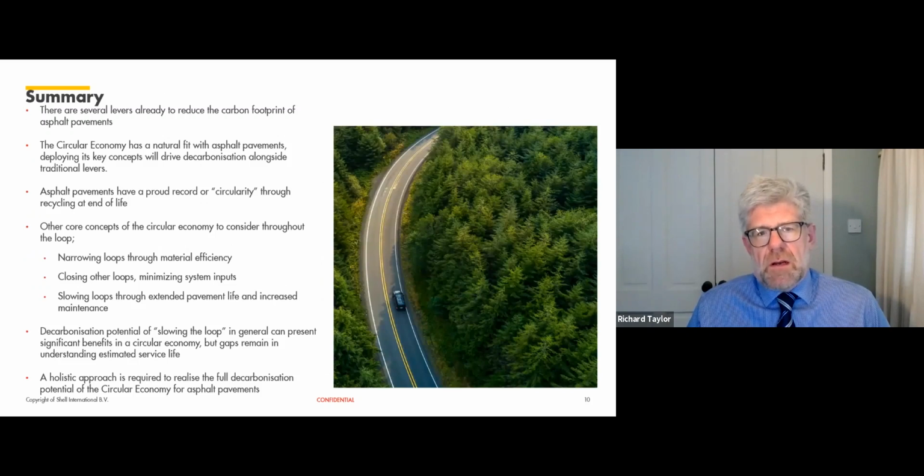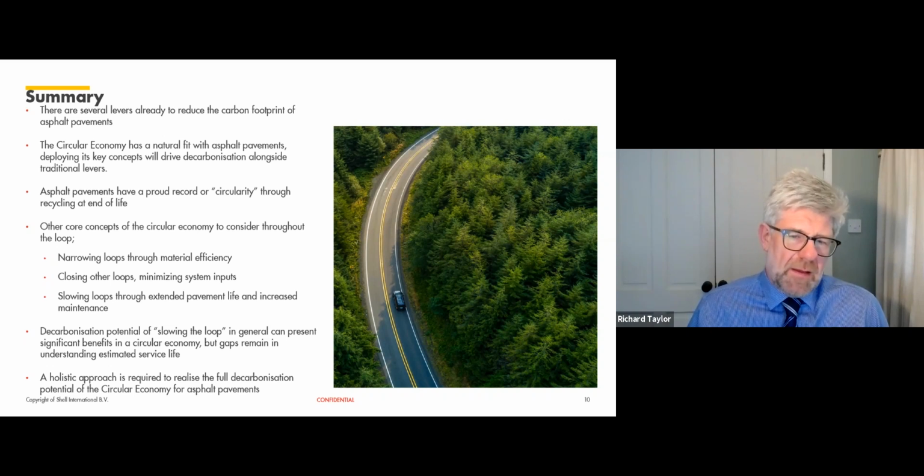And so, just to conclude, to take two views of the asphalt, bitumen and paving world, we have a decarbonisation view of the world, and that view is already quite well understood. I think it's fairly clear what needs to be done: switching fuels at burners, moving the material using more efficient transport or with cleaner fuels, and changing the binders to bitumens with a lower embodied carbon are probably the three most significant levers, alongside other levers like incremental changes in fuel, etc.